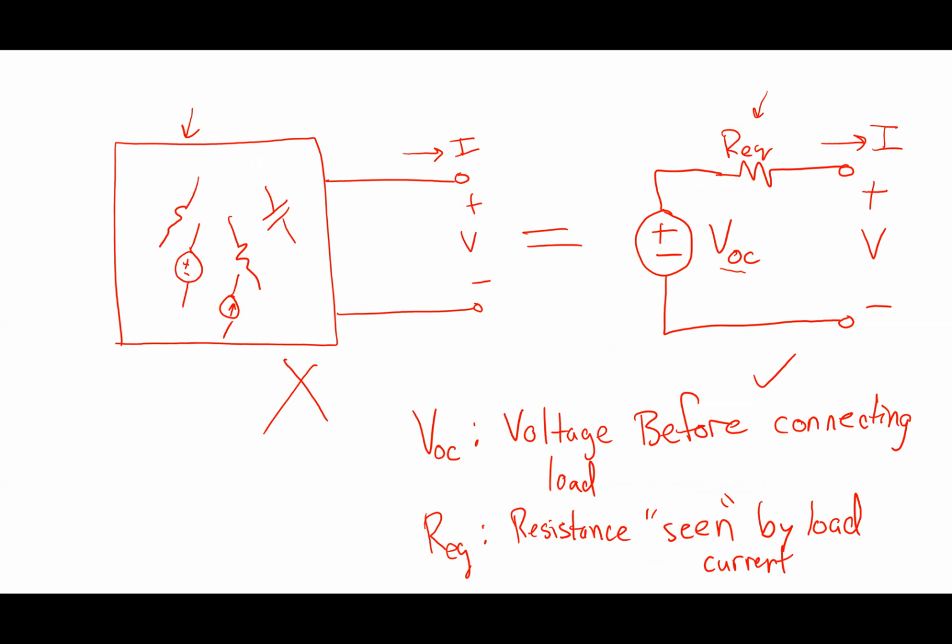Thevenin equivalence, you say I've got a network that's complicated. I don't even need to know how the stuff's connected in the network. It's just connected in some kind of goofy way, right? I've got resistors, capacitors, sources, all that kind of stuff that's somehow connected. I don't know how, but somehow I can get it down to the open circuit voltage and the equivalent resistance. The equivalent resistance, this is the important point.